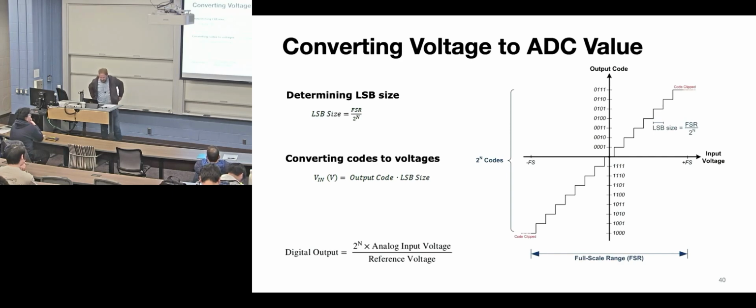It's important to be able to walk yourself through this: how to convert from analog voltage to a digital voltage. This is just a different way of showing that scale in case we had a negative reference frame. So this would be a negative reference, positive reference. Normally we saw before there was always a zero reference, so the reference was always ground, but this is just a different way to draw it. So here we have some negative values. So we have some negative voltage that turns into a binary value if you wanted to. So you'd be going that way instead of that way.